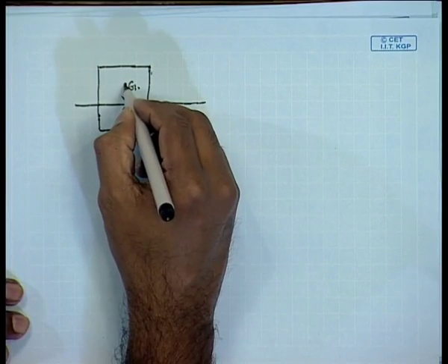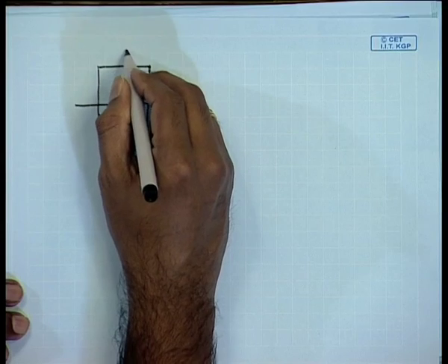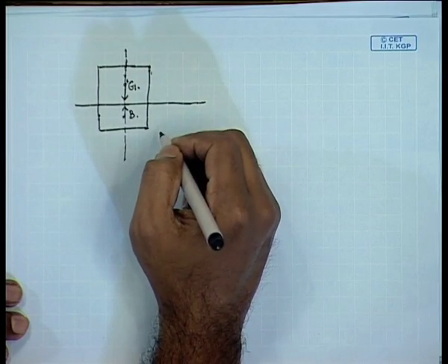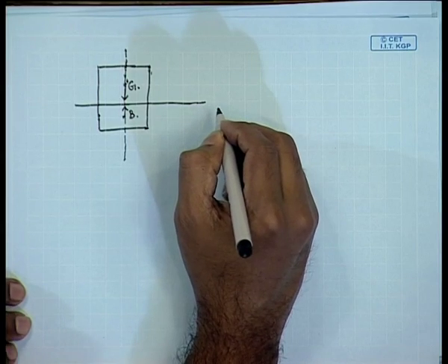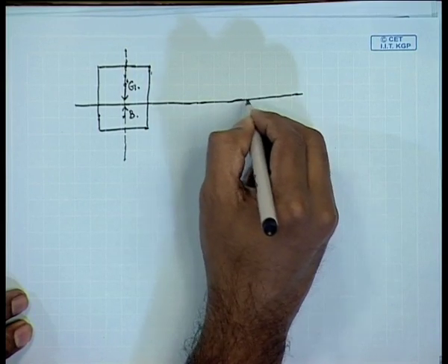Now, the center of gravity of a ship depends upon the weights on the body. It does not have anything to do with the water or the upward force from water. It has to do with just the weights that are placed on the body. So, when you place weights at different places, you get the center of gravity. So, you have in this case, for instance, center of gravity and center of buoyancy in the same straight line. Then if they are in the same straight line, they do not produce any moment.